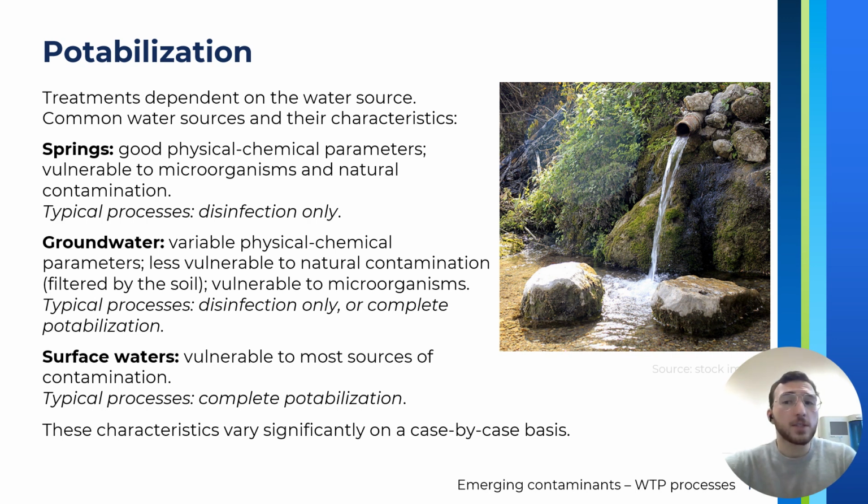Springs have generally the highest quality waters found in nature. This is thanks to the good physical-chemical properties attributable to the relatively lower anthropic contamination these springs are generally subjected to, while still being vulnerable to potential contamination by microorganisms or natural sources. Springs often only require disinfection to be fit for human use, although other processes such as flocculation and sedimentation may sometimes be necessary. Water wells tapping into groundwater sources are among the most common sources of water for human use.